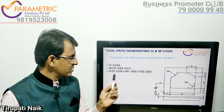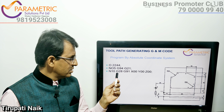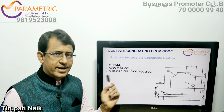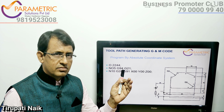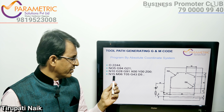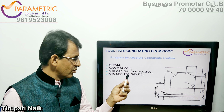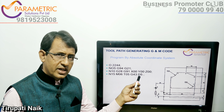Next, for the tool reference, block number N10: G28, G91, X0, Y0, Z0. This is the one statement for taking the tool reference, that is the tool position, called the turret. The next step is N15. Now we are going to change the tool in the turret, that is M06, fifth tool, T05, then tool length compensation G43 and offset D5.